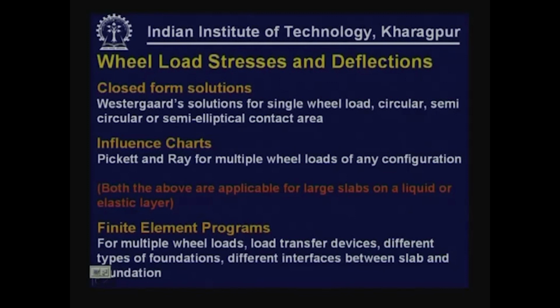There are a number of finite element programs that are also available at present, which are capable of solving the pavement systems for multiple wheel loads, for different types of load transfer mechanisms. The two types of solutions, in the form of closed form solution and in the form of influence charts, are not normally capable of handling different types of load transfer mechanisms.